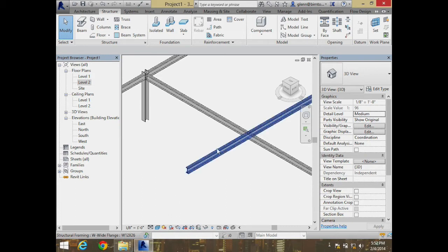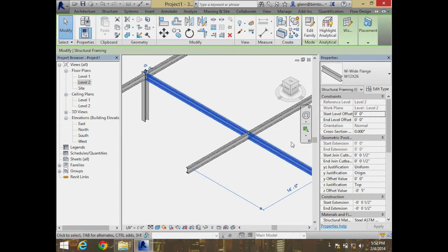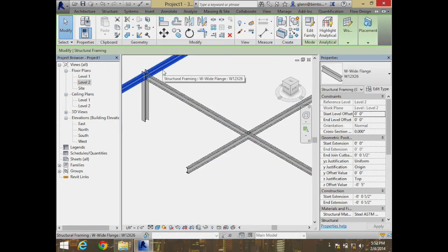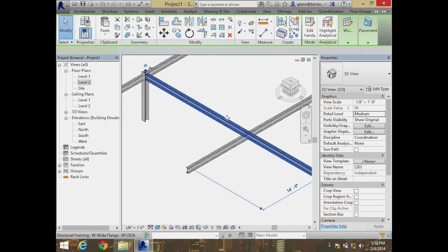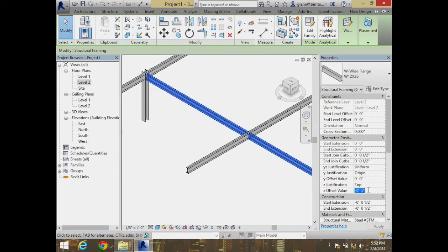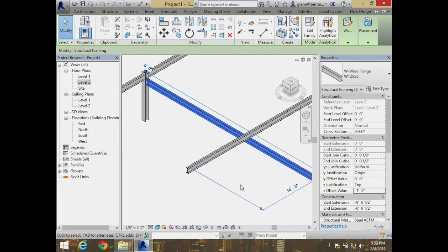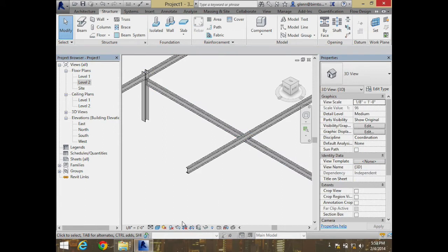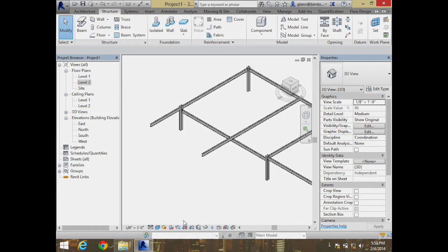So what I can do is say that this beam over here, as opposed to being -5 inches, what do I have to allow? This is like another 12 inches tall. So I have to basically lower it another 12 inches and make it -17 inches. Okay. It'll ride underneath. Architecturally, we're going to have to worry about that a little bit in terms of the height of the doors and the ceiling and stuff like that. That's going to be riding a little bit low, but that's okay.